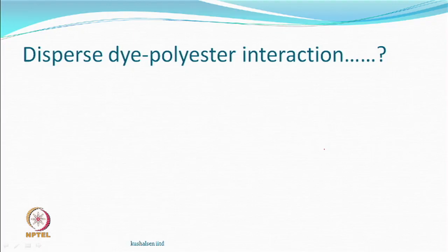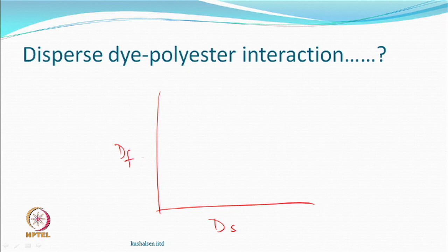But the important part here is the curve, the relationship between dye in solution versus dye in fiber, when you are dyeing these materials with the disperse dye. Then we see a curve like this. Obviously, dye cannot go into the crystalline portions. So, there is a space which is the amorphous phase, the dye diffuses in there, and this curve talks about something called a partition coefficient.